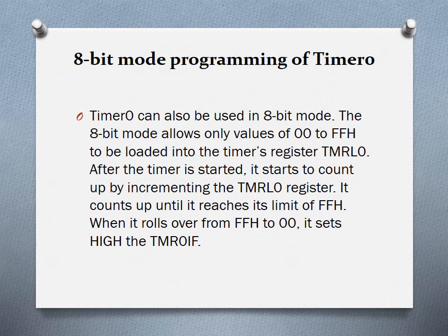Another register is a CON register, the control register: timer 0 control register, timer 1 control register, and so on. These registers will hold some status values. This will have some on and off values, and all these values will be present inside the timer CON register.